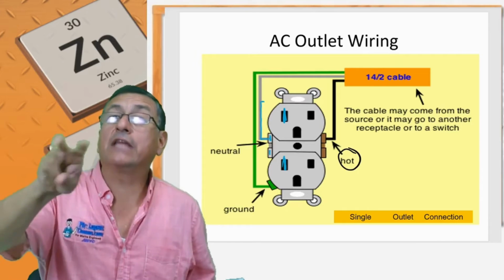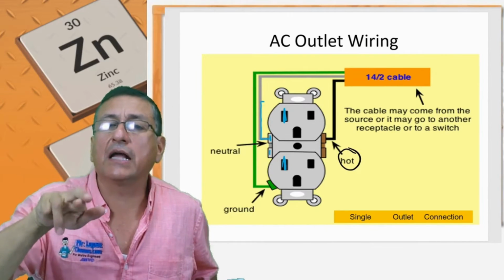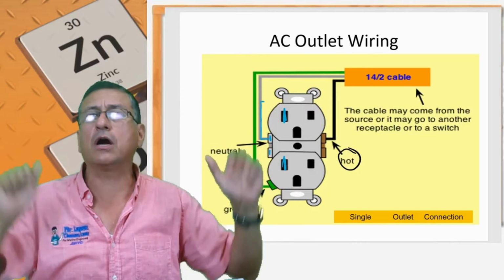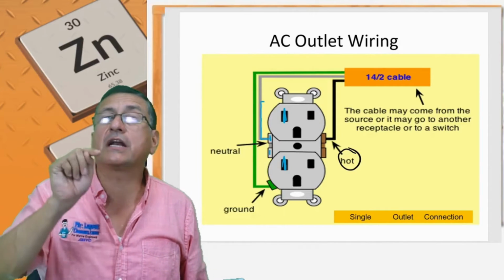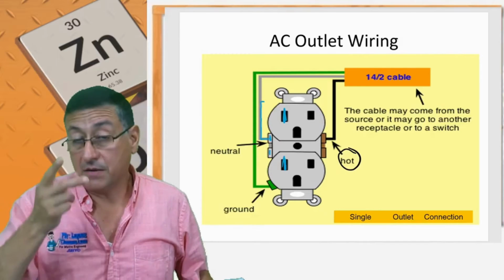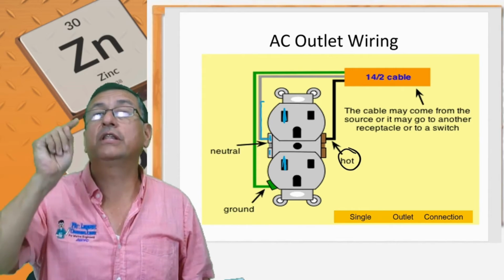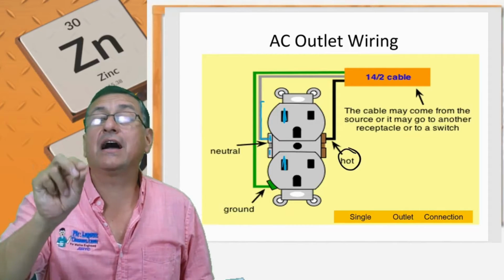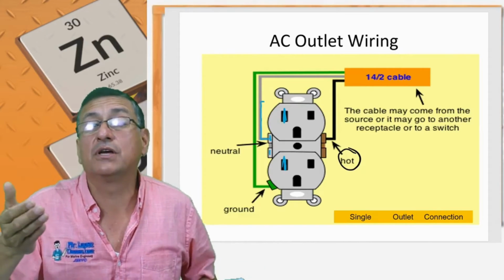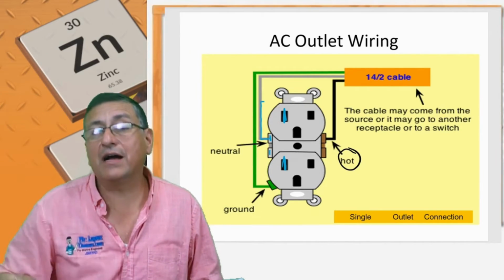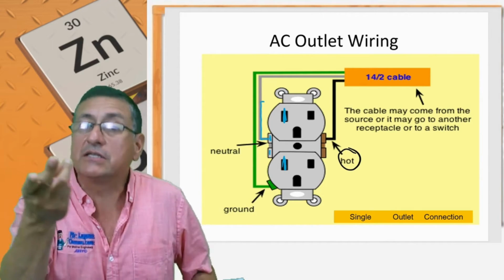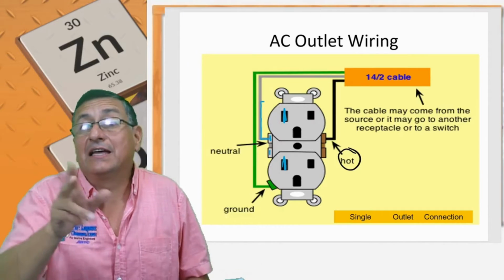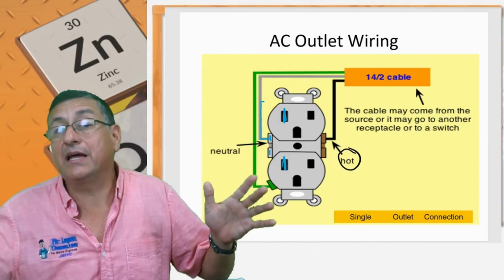Okay. Right now, the outlet is wrong. The neutral and the hot are switched. And I have two blowers running 24 hours. But for those blowers, the return, remember, is always through the neutral. And right now the neutral is hot and the hot is neutral. Right now, I have a return of 3 amps, 5 amps in the neutral bus bar. I have a current in the neutral bus bar because those outlets are switched. And what happens if that neutral bus bar is connected with the ground bus bar?